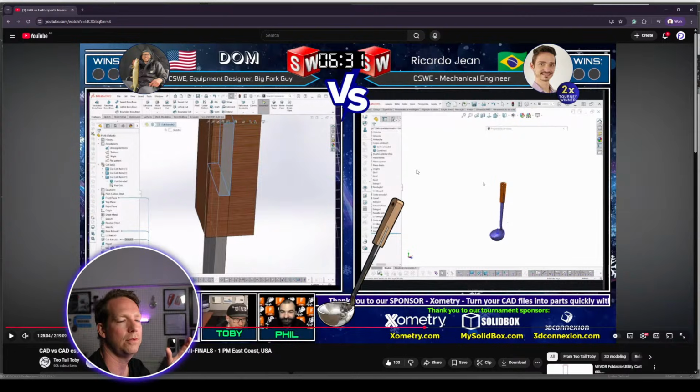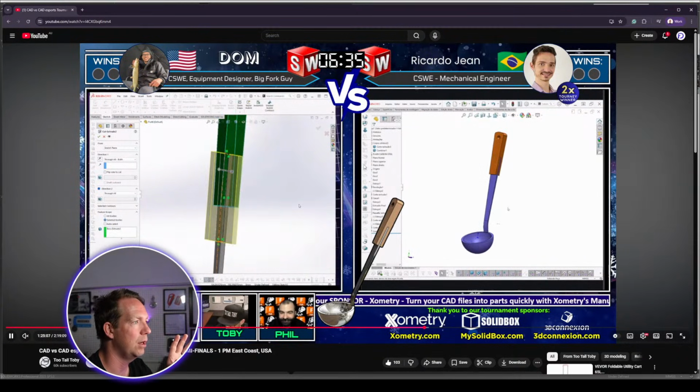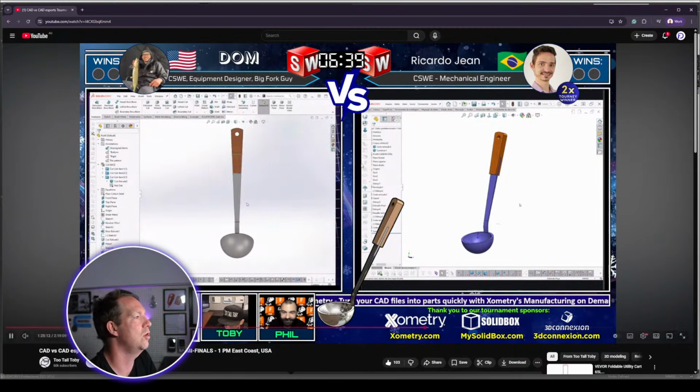With a combine tool, if you use combine and a subtract, when you subtract the body, that body disappears, the one that you're using to subtract. But using the indent tool, that doesn't happen. The body stays there. So in this kind of example, it's perfect. You could do an indent for the handle, for the metal part into the wood. Keep all the wood there, keep the metal there, just remove the part that is overlapping.